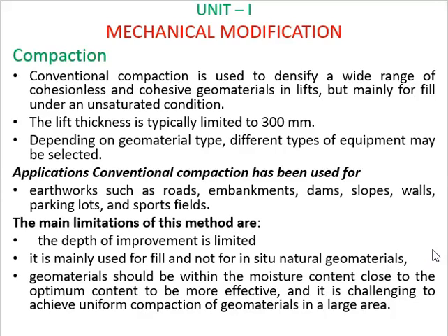As the maximum density will be obtained at optimum moisture content, it is difficult to bring uniform moisture content throughout the soil and also difficult to achieve same degree of compaction effort at different depths of soil deposit or layer.